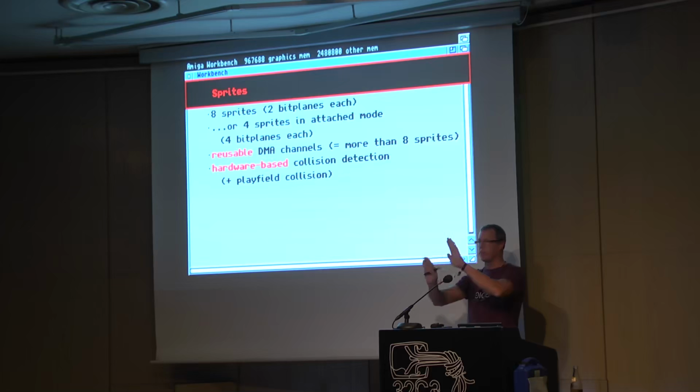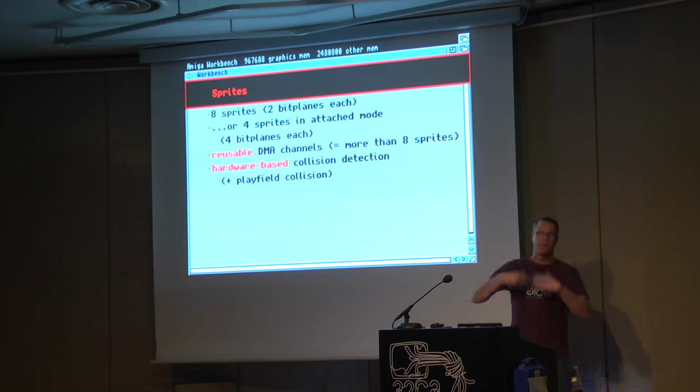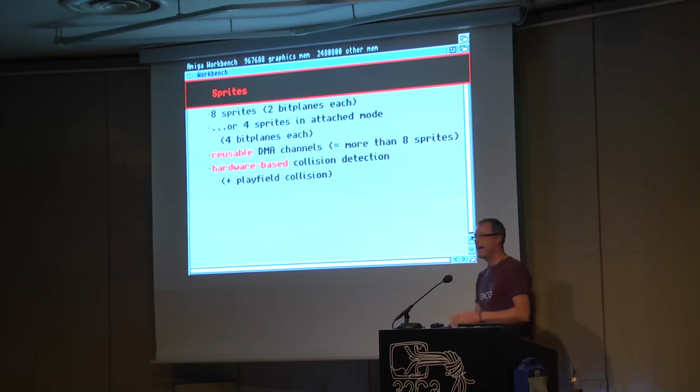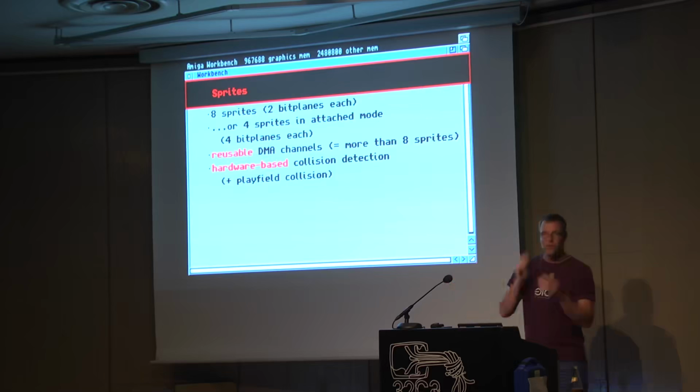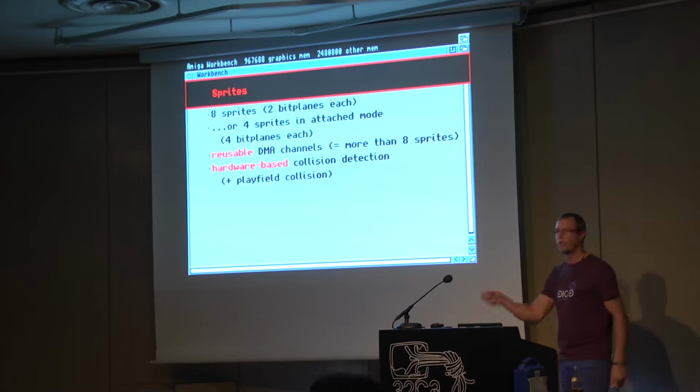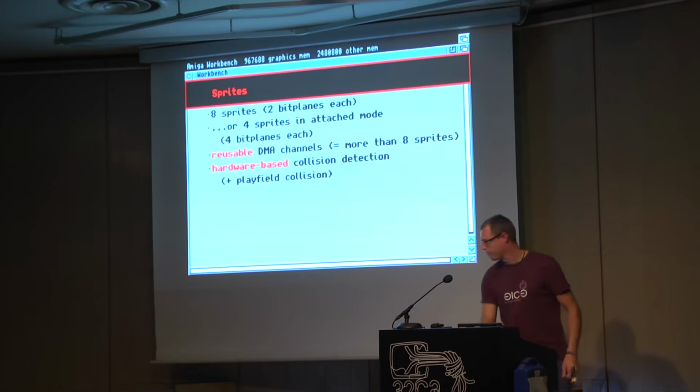Think of a game: something is moving, and if they collide, then something happens, something explodes, or you gain some health points or stuff like that. The collision of the 2 sprites was actually done by hardware. During screen build-up, or during combination of bit planes, it compared each bit to each other, and then it recognized there is a collision. And there was a register, a special function register, a custom chip register, which you could query with the CPU and see, okay, there is a collision now.